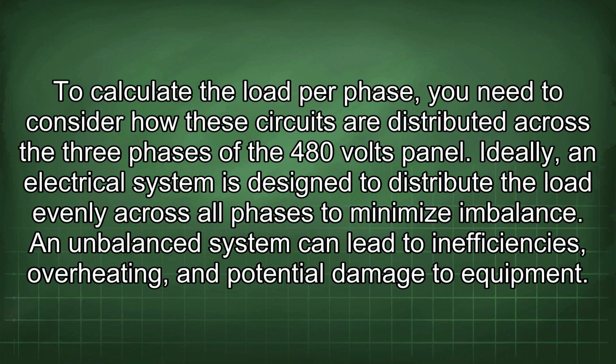To calculate the load per phase, you need to consider how these circuits are distributed across the 3 phases of the 480 volts panel. Ideally, an electrical system is designed to distribute the load evenly across all phases to minimize imbalance. An unbalanced system can lead to inefficiencies, overheating, and potential damage to equipment.